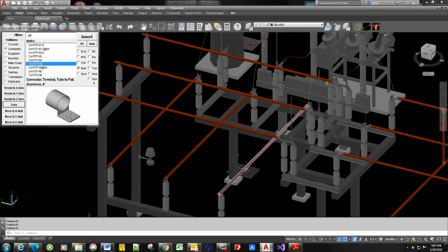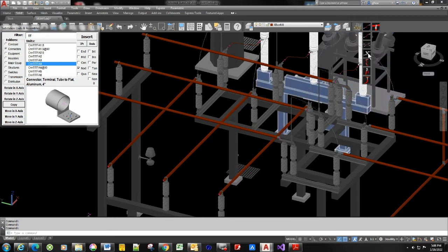So what we need is a jumper from this pipe to this pipe, from this bus to this bus, and generally I look at that as it's coming from the bottom one to the top one. So I labeled that a riser bus. Now you can go either way, but that's the way I looked at it initially. So if I go back up here to my jumpers, I come down here, I find that I have a riser, and you can see the icon kind of looks like that.